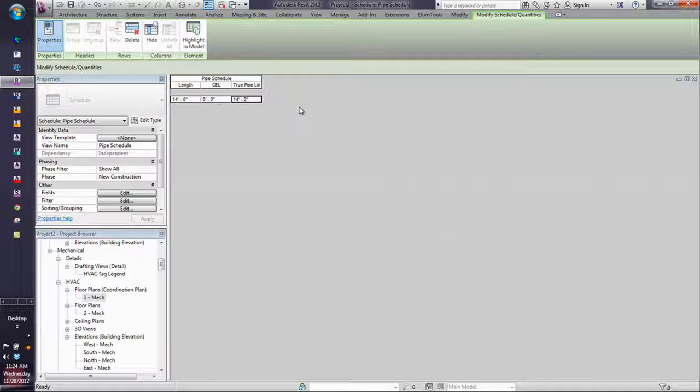And what we do is if you want to show the carrier in there, you can turn it on and off. We also have families that have the carriers and families that don't. So if you put one in with a carrier, then the connection isn't at the back of the plumbing fixture. It's actually on the carrier itself. So that way you don't have to do all this extra pipe routing between the plumbing fixture and the carrier. We just did all the solid modeling in between.